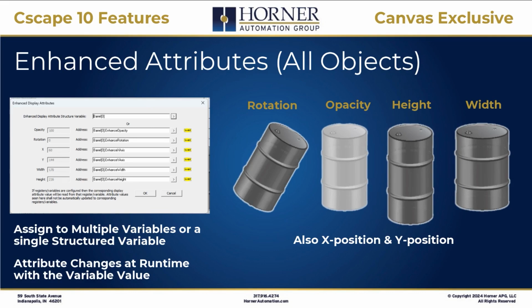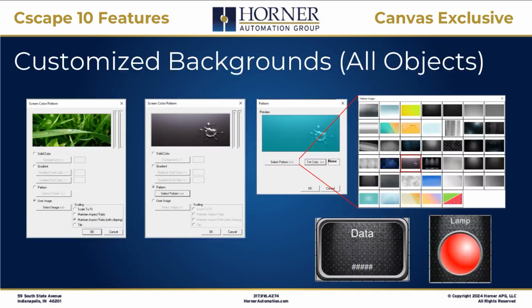Or if you are going to be manipulating multiple of those attributes, and you're using an IEC or a variable-based advanced ladder, you could also utilize a structure-based variable so that you can quickly and easily access all those attributes by assigning a single variable. So that's definitely a useful feature that applies to all objects in Canvas with Cscape 10.